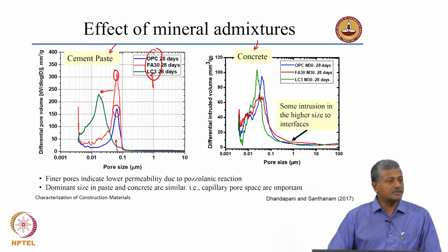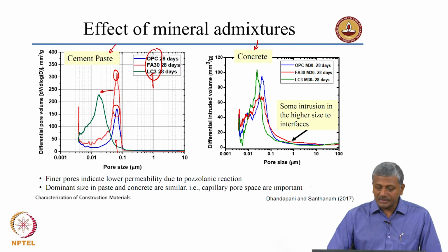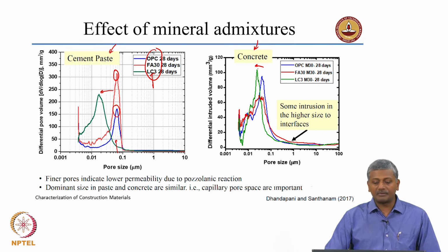You are shifting your size to a smaller value, which indicates that your pore system is getting finer and finer. Do we see the same effects in concrete? Yes, to some extent. We see the same effect in concrete with respect to ordinary Portland cement and fly ash,